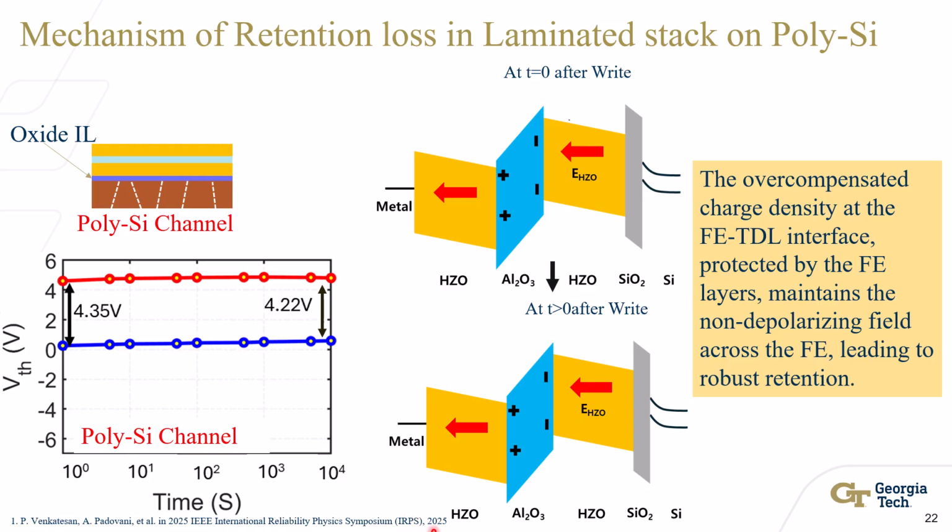In order to understand this, we did some modeling, and we presented that work in our previous work at IRPS 2025. Without going into much detail, the brief mechanism is that there are some charges present at the ferroelectric dielectric interface, and these charges lead to an enhancement in memory window, as I mentioned earlier.